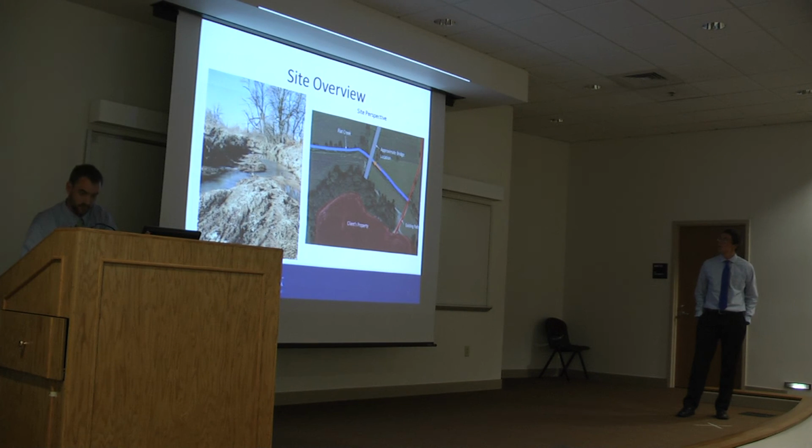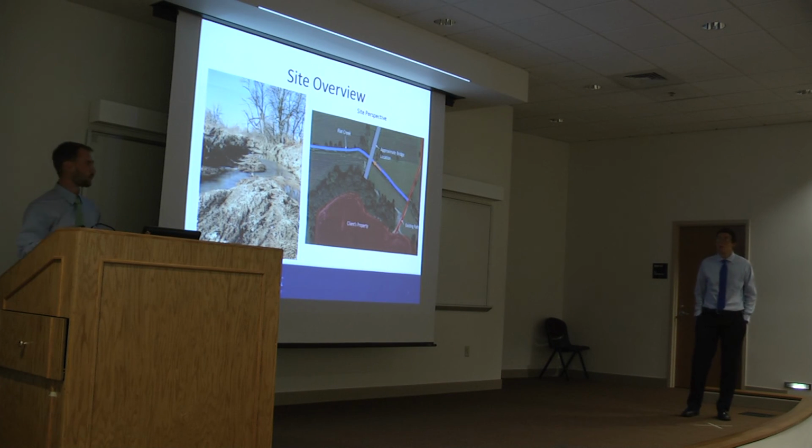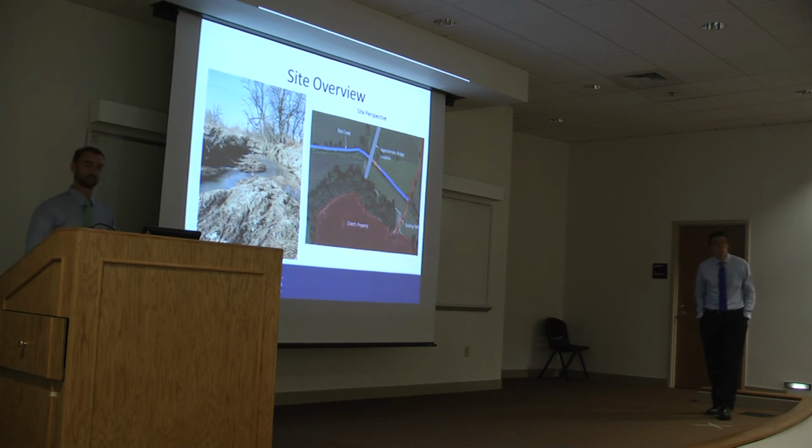Yeah, if you look in the distance here, about where the bridge is going to go in this area, we measured 10 feet from the bottom of the creek to the top of the bank. The water depth varies because it goes up and down, but I think at the bridge itself, the water depth is about 2 to 3 feet. So from the bottom of the channel to the top of the bank was 10 feet.